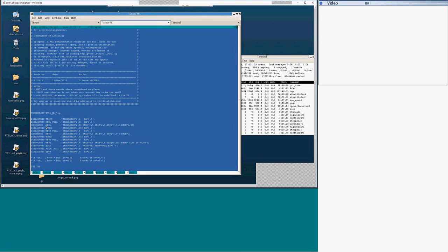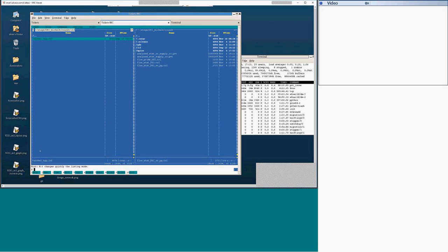In your case, you see conductor layer names and via names. They match what we have in the layer map file, so that's a good practice. If they do not match, you would have to create a layer mapping file, but that's not the case for you. So that's technology data. But let me get back to the technology data.